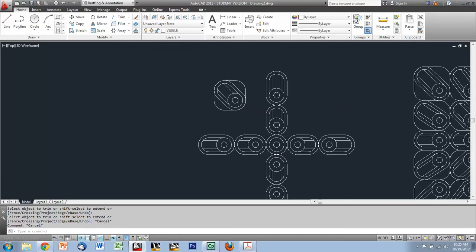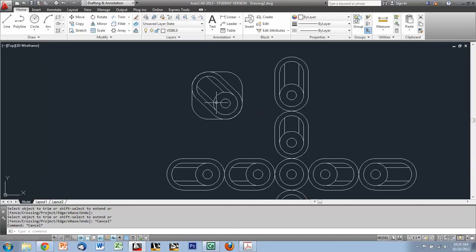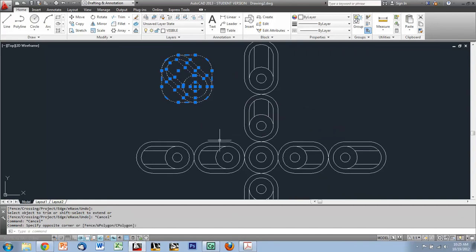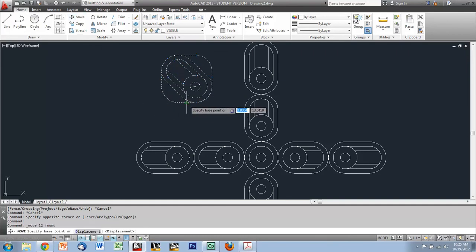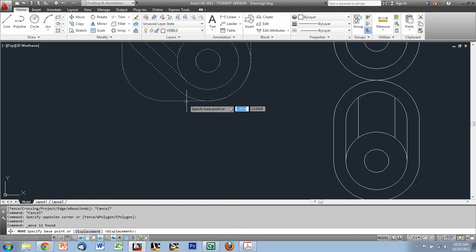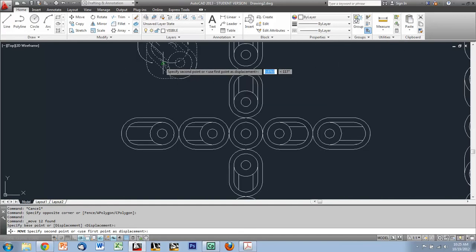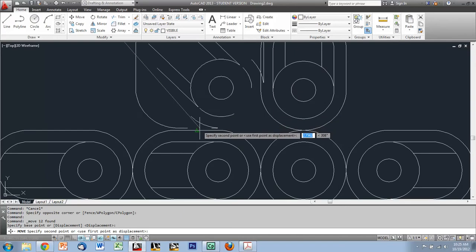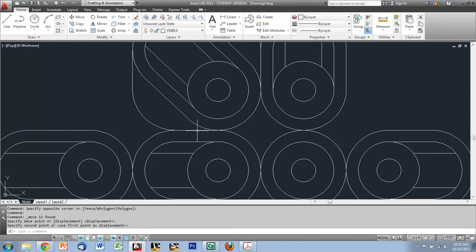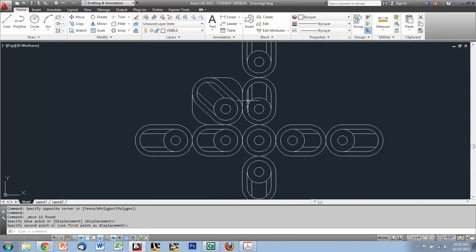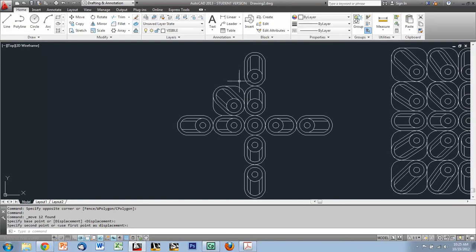And there you can see we've got that first box ready to go, so I'm going to move it into position. So I'm going to select the whole thing, and I like to use the center point of this link down here as my moving location. So I'm going to use the move tool, and I'm going to start right here. Make sure you get the triangle so you know you have the midpoint of that edge of the rectangle. So I'll click there as my start point, and down here I'm going to use that as my end point. And you'll see that it drops it right into perfect location.